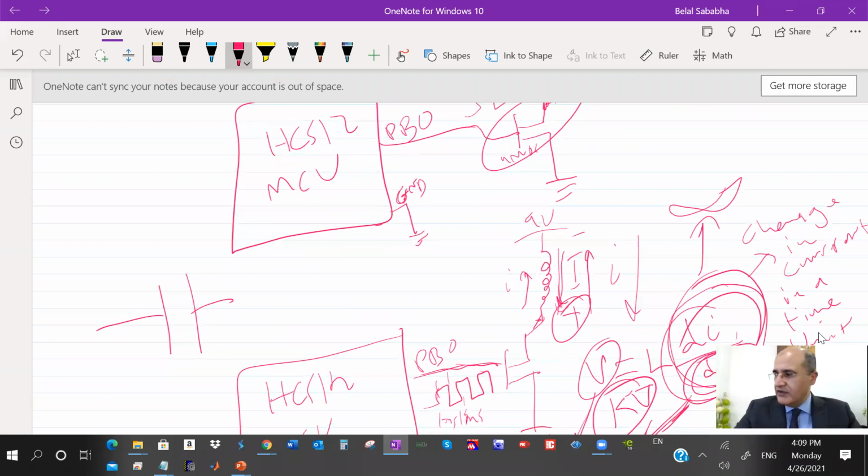Usually, in some circuits, they have a diode connected across the inductor or the motor. Well, this could be an inductor if you want to generate high voltages, right? Usually, we use a diode. They call it a freewheeling diode, or a flyback diode. This is to cause the current to go through this path, okay, to protect. And the voltage can rise, without freewheeling, up to kilovolts here.